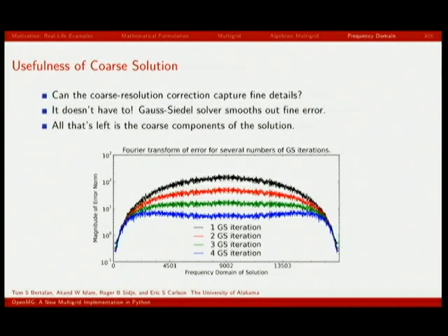In the context of multigrid solvers, the iterative solver is not called a solver, it's called a smoother instead, because iterative solvers like Gauss-Seidel, which is the iterative solver we use, do a really good job of smoothing out the high frequency error in the initial guess, but a really bad job at smoothing out the low frequency error, which is the big changes in the solution. Because they really quickly take out the high resolution error, it's safe to represent the problem at a lower level of resolution to get the correction vector.